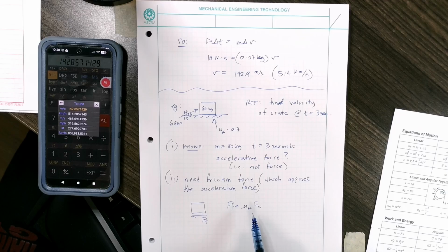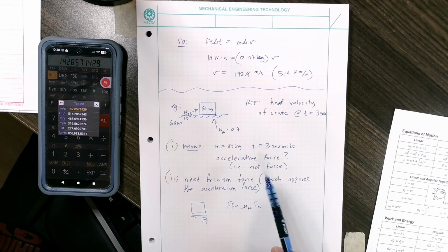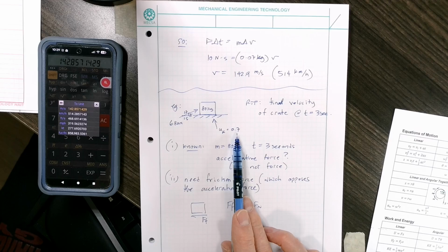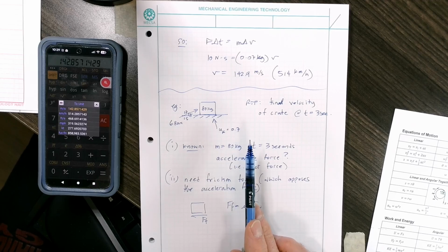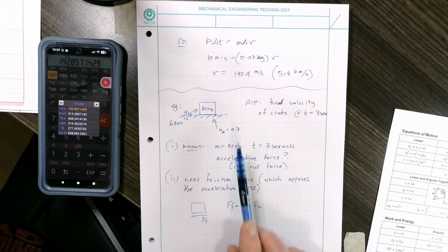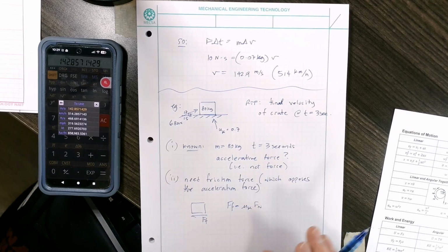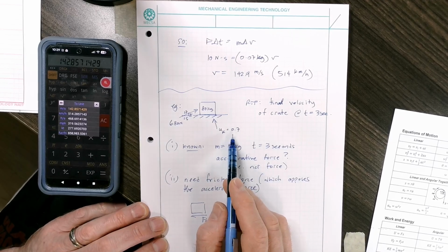No. You better make sure it's 0.7, because if it's actually 0.5, that's a significant change. 0.7 to 0.5, what is that? 20% less or something? That's a big 20% error. So even though it's a decimal, don't just be cavalier about the friction coefficient. Go test it. You learned how to test friction forces in statics, okay? Go and do a test and get the actual friction coefficient.